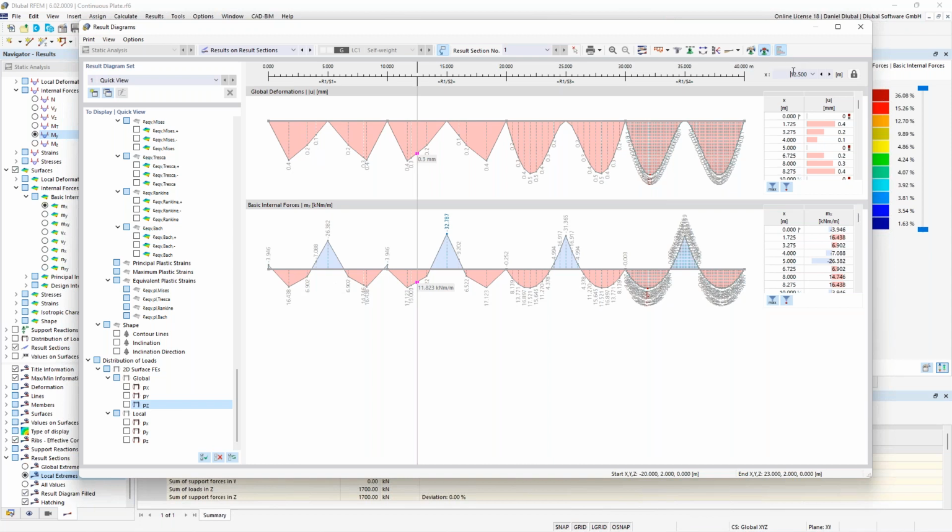The same here, but now it becomes interesting. Here we have 15, so this is a quite big difference. But the value which is more correct. So in order to say what I want to say with this message is a finer mesh does not necessarily lead to better or more accurate results. This is something you have also to remember. However, FE nodes should also be close to expected extreme values. And this is important to know.